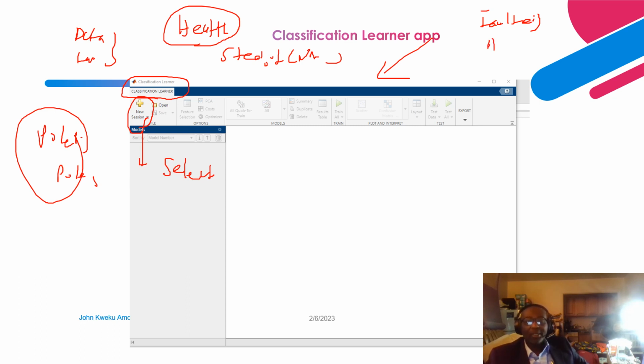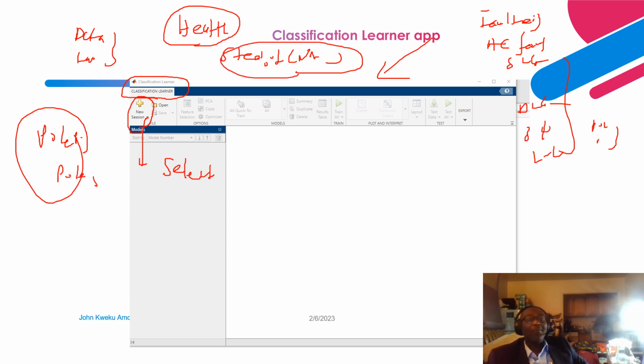For instance, in the AC industry, I can have a single line to ground fault, double line to ground fault, three-phase fault, and line to line faults, so 4 faults. The same thing in the HVDC industry: I have a pole to ground fault and pole to pole fault. So it's very applicable to whatever industry you have. You can have different conditions of faults that you want to process. Your steady state, your non-faulted state, is the state that does not have a fault.